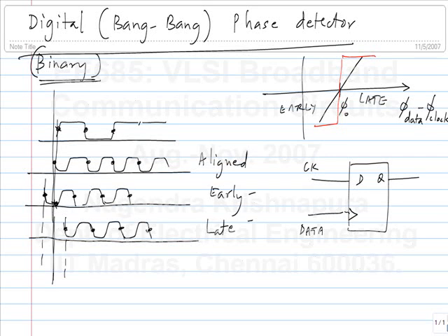No, see, jitter is just phase. That only means that the phase of the data or the phase of the clock is not uniform. Now, if you give jittery data to a phase detector, it is supposed to measure the jitter also, right? So jitter is part of the phase. Maybe the clock is not some fixed phase, but also has some phi of t. But a good phase detector is also supposed to measure and respond to this. So that's not a problem. Maybe that phase jitter is a problem for something else, in which case you have to clean up your system to get rid of that.